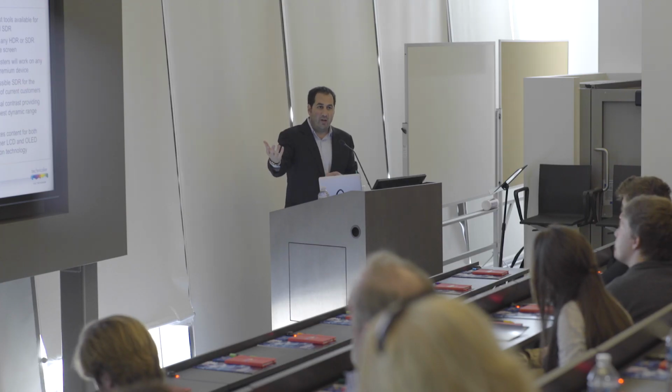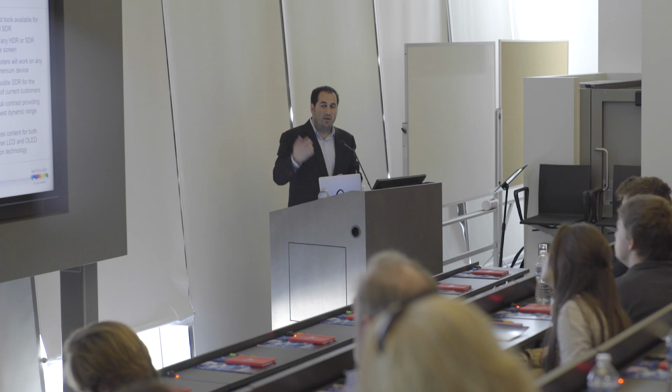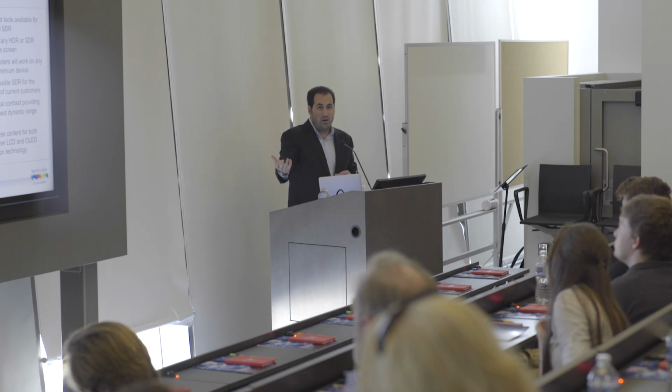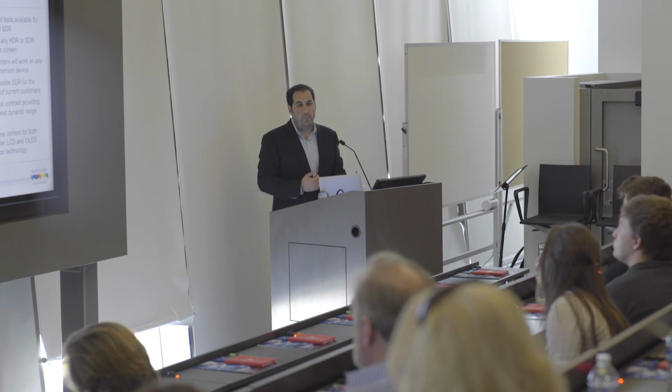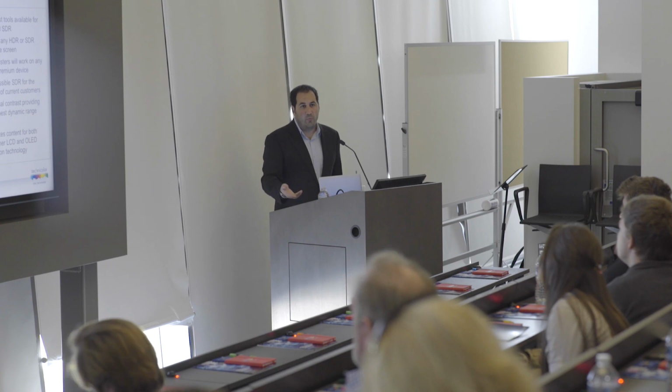So for a lot of distributors, one of the technologies that Technicolor has developed for helping boost that open ecosystem is a way to take both masters and combine them into one signal. So now that one signal will be directly backwards compatible to the SDR home, and the metadata that we generate, which is the delta between the SDR and the HDR grade, can now be distributed to that home as well. And as it gets recombined on the back end, you have HDR for your HDR customer. As it doesn't get recombined, because the SDR content is the base, it ignores the metadata, all of your SDR screens work as well. So now one signal can distribute both pieces of content to the home.